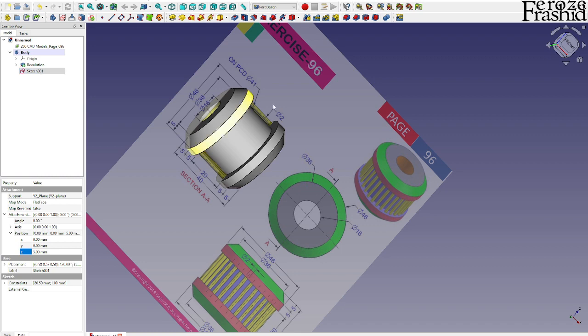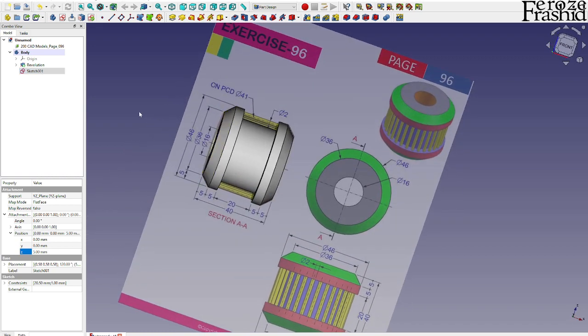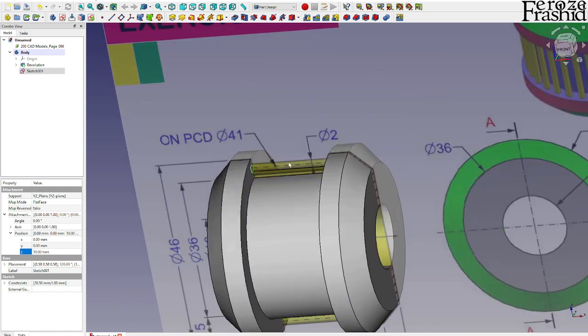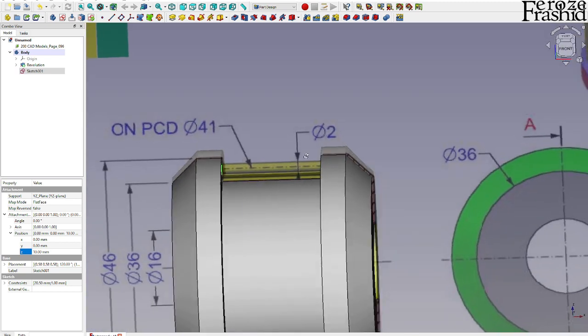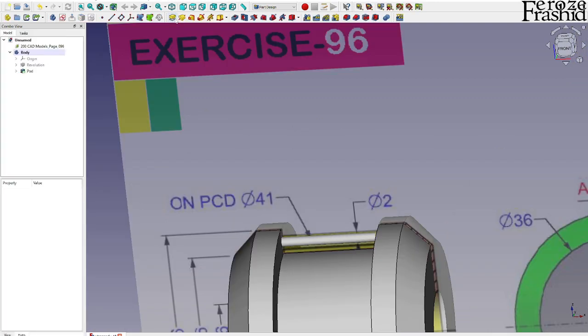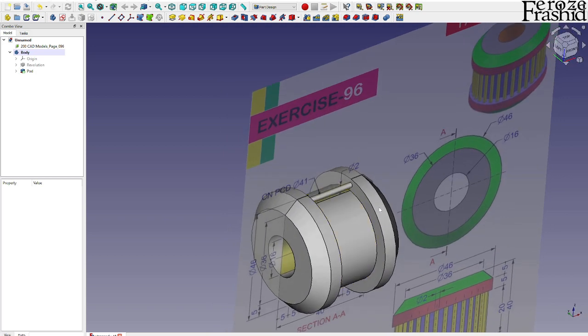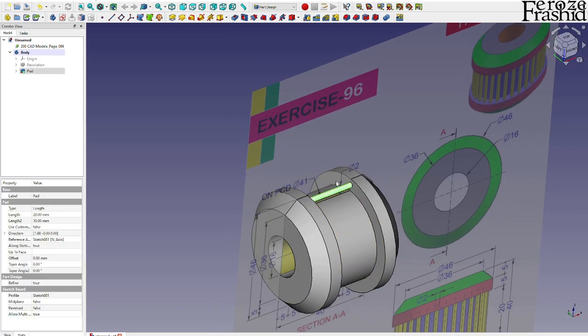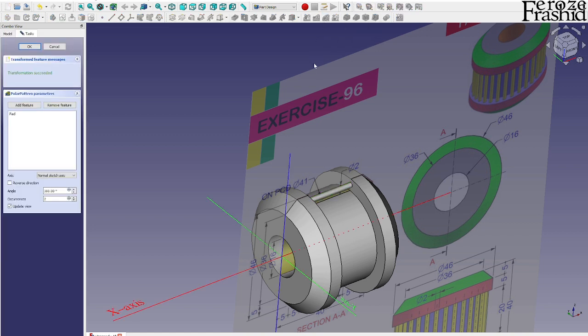Now where is that? That is kind of there. How about I say 10? And that puts it on this face, and that's what I want it to be. Now I want to pad it for 20. So that is our first cylindrical bar, and then I want to revolve it around there with this polar pattern. Let's go ahead and make this pad.